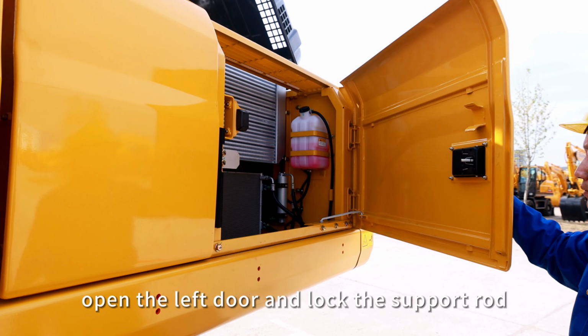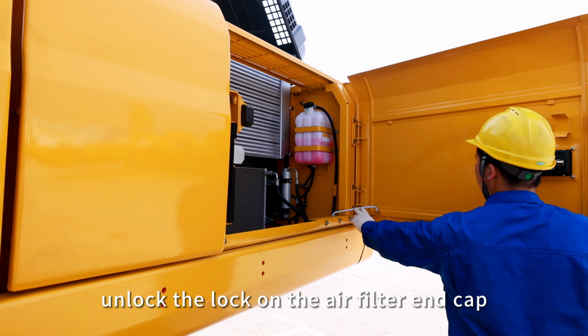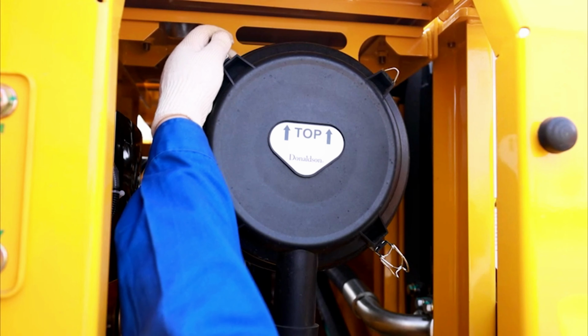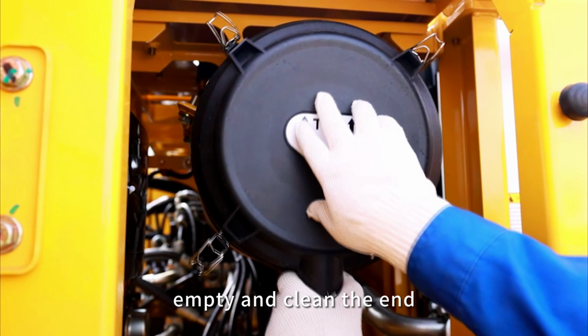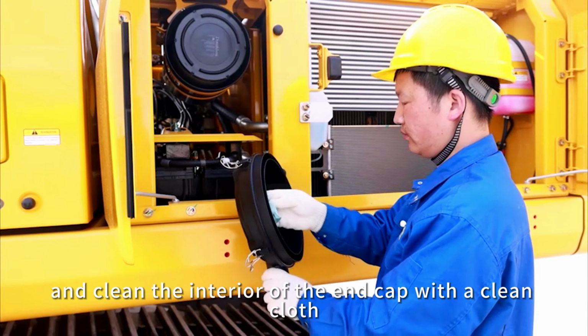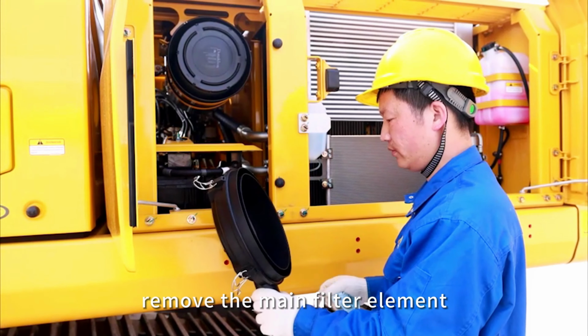Steps: open the left door and lock the support rod. Unlock the lock on the air filter end cap. Remove the air filter end cap. Empty and clean the end cap and dust collector valve, and clean the interior of the end cap with a clean cloth. Remove the main filter element.